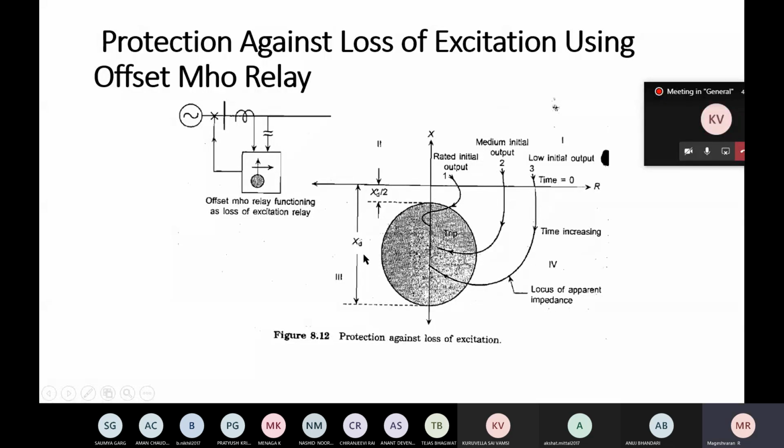Because in the stator winding, even though in the explanation I said Z, actually here X is important. Just now, for the power swing, even though I plotted ZSA and ZSB, I assumed them as reactive. Here also, the transient and subtransient reactances are assumed.